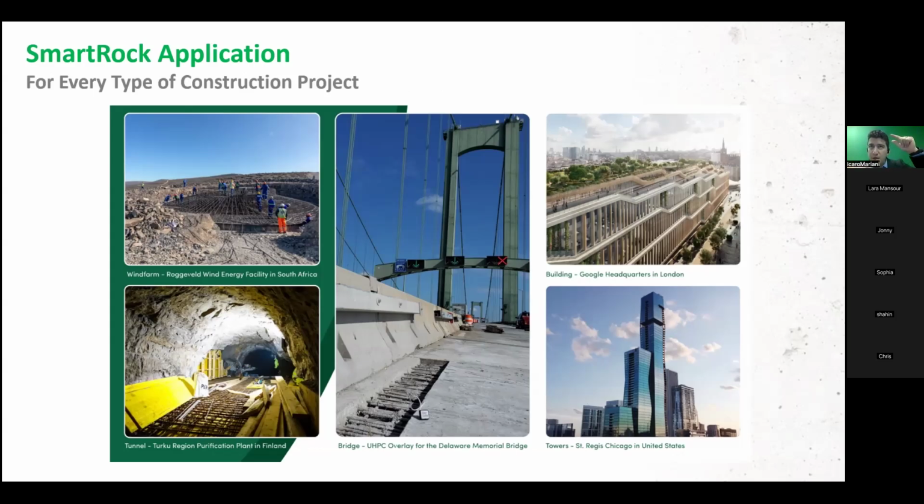If your temperature difference is too high, you're going to have cracks in your concrete. So you need to respect a 35, 40, 45 limit, depending on the spec, to prevent thermal cracking. And that's why the sensors are being used, because the pedestals are huge. So they need to put a sensor in every single pedestal to track these differences.